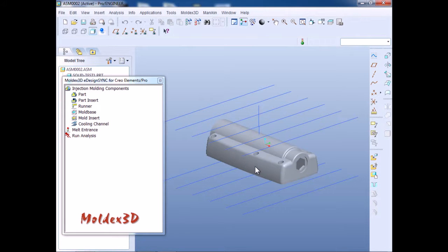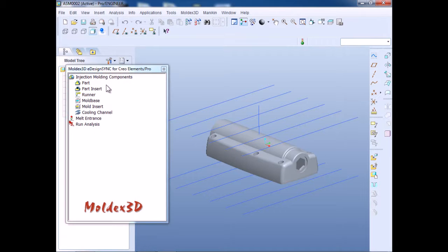For this model, which is a solid part model, there are two kinds of line structures, runner lines and cooling channels. We will set the part material properties first, and then show a step-by-step setup for the 3D pre-processing of the runners, mold base, and cooling channels according to the 2D line structures. Now we will set up the part material.